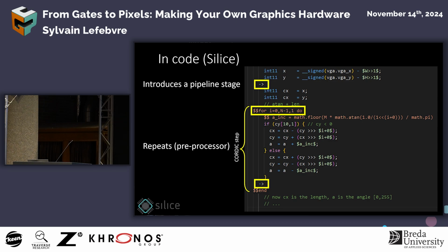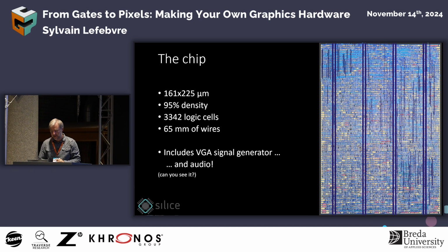By the way, this here is 1 iteration of the CORDIC algorithm, so you can see it's very, very simple. It's doing a vector rotation to get the vector back to 0 while counting the angle. And when the vector is back to angle 0, the x-coordinate is the actual length of the vector. Right? That's a very neat approach.